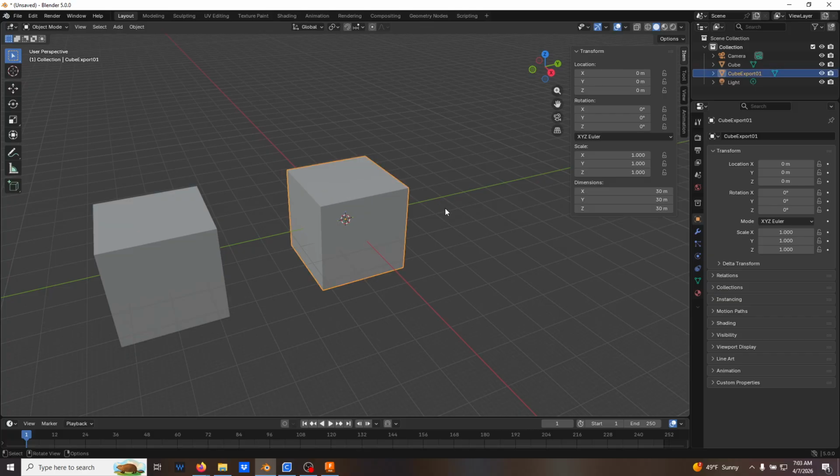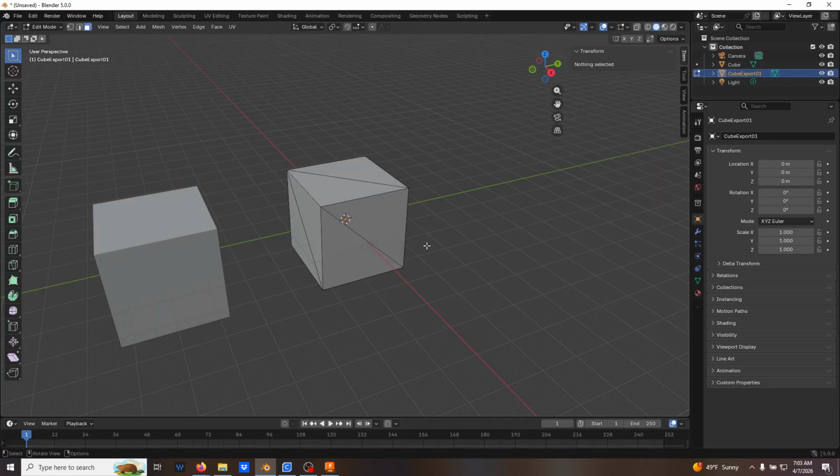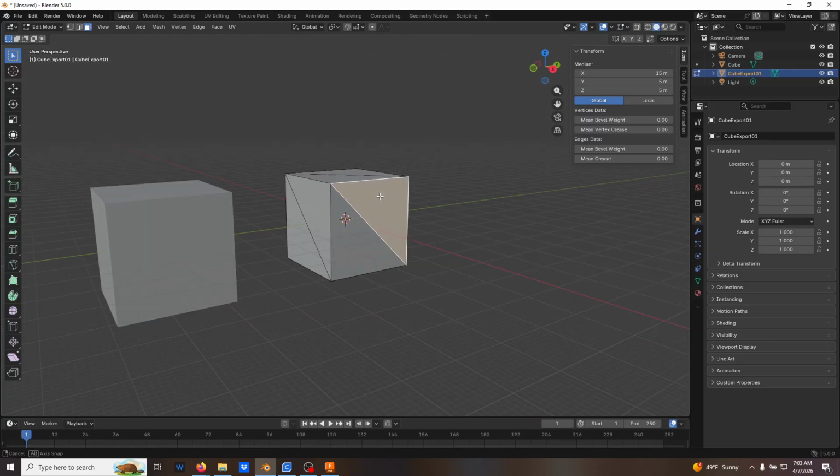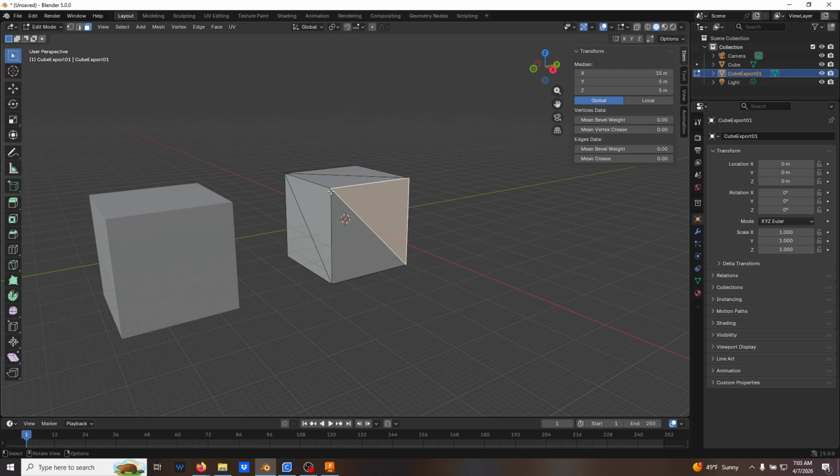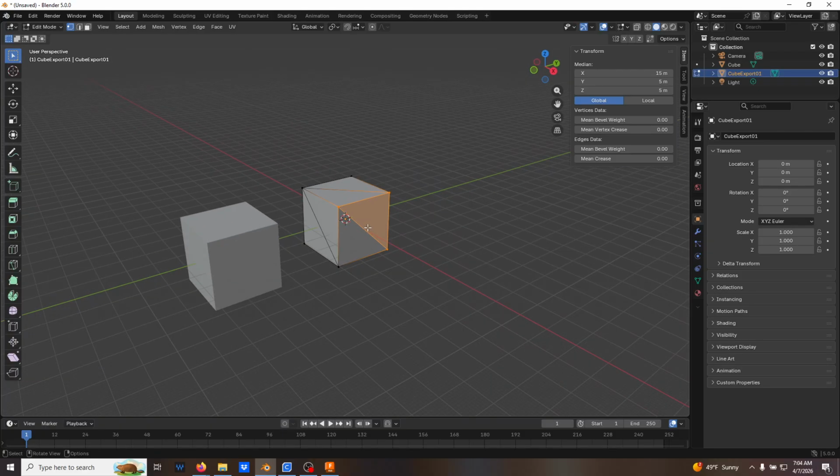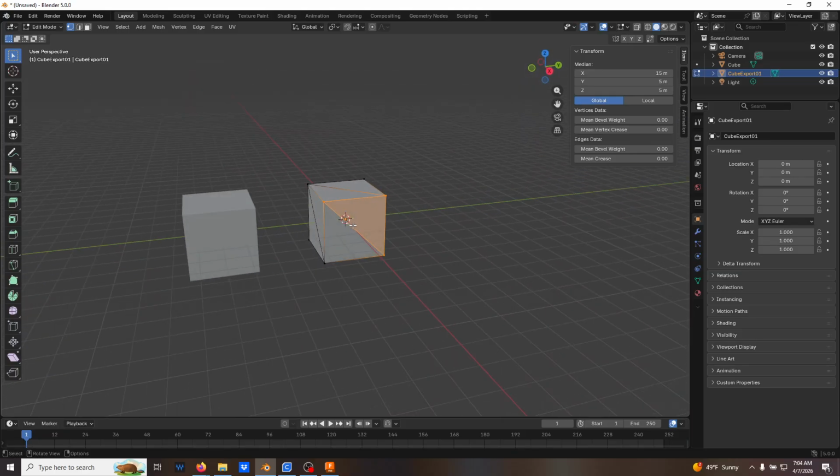Okay, so now I'm going to select this cube export and go to edit mode for that. When I do, what you'll notice is that it's now made up of triangles. This highlights an important thing I like to mention about mesh modeling: when you create an STL file, what you're doing is taking your solid file and turning it into a bunch of polygons. This is the same cube that I exported out and then brought back in, but when I brought it back in, everything is triangles.